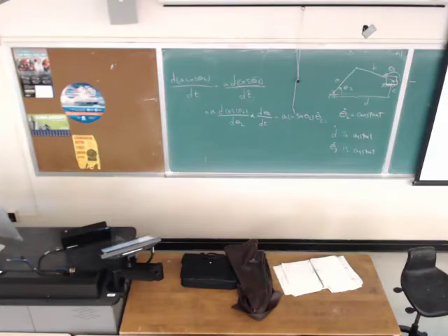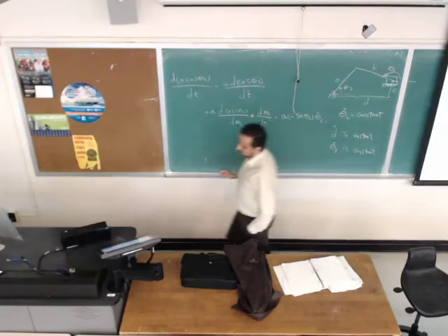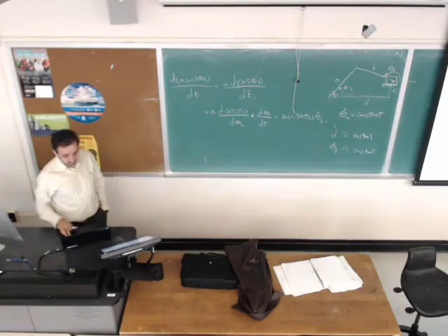Can I say that d dot is going to be constant while the mechanism is running at the constant speed? No. Why is that? Because theta 2 and theta 3 values are changing in this system of equations. So although theta dot 2 is constant for different values of theta 2, the values on the right side and the left side are changing. So we will get a different result for d dot and theta dot 3 at different values of theta 2.